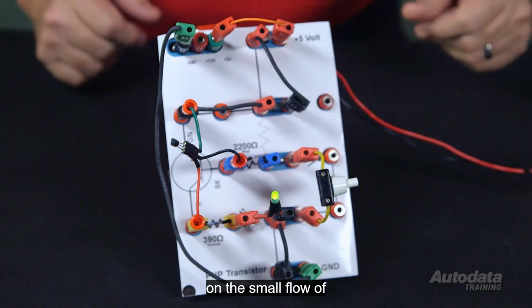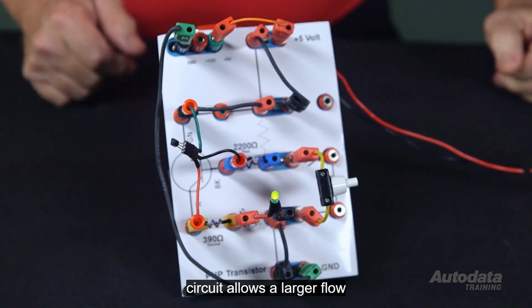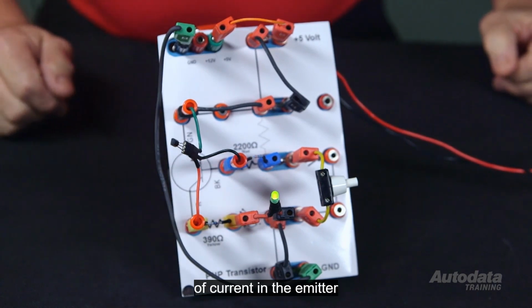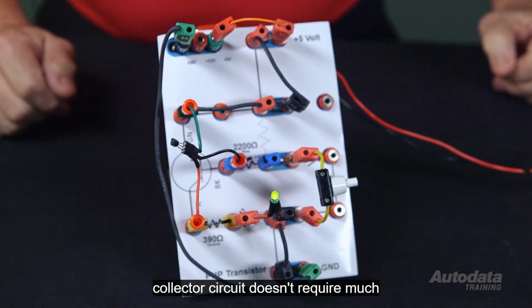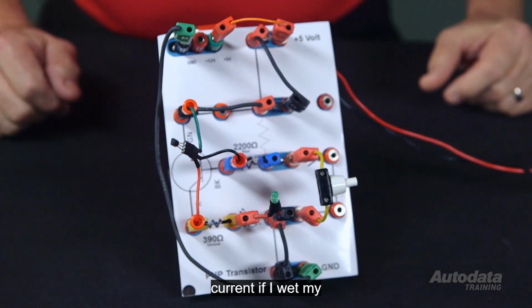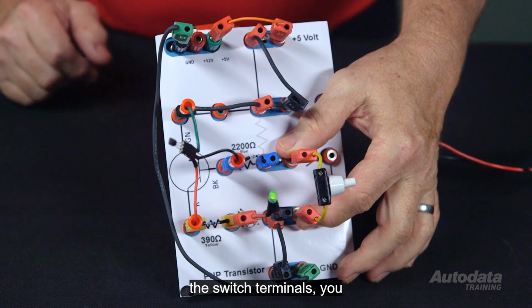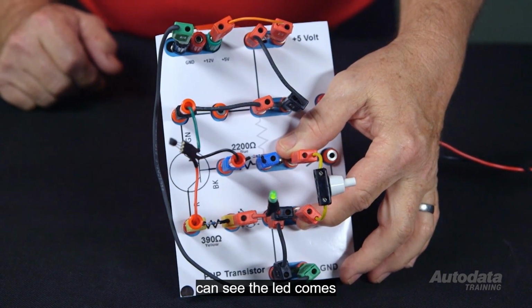When I turn the switch on, the small flow of current in the base circuit allows a larger flow of current in the emitter-collector circuit. It doesn't require much current. If I wet my fingers and put it across the switch terminals, you can see the LED comes on.